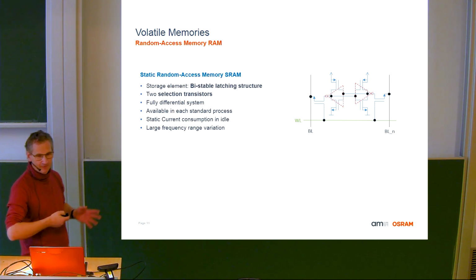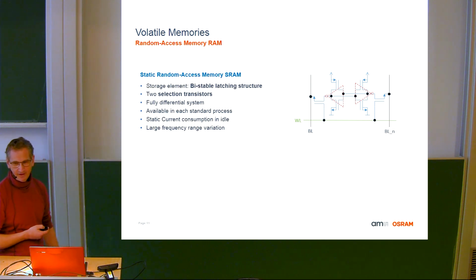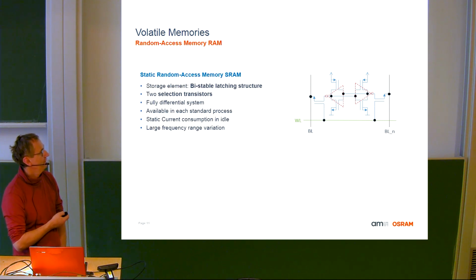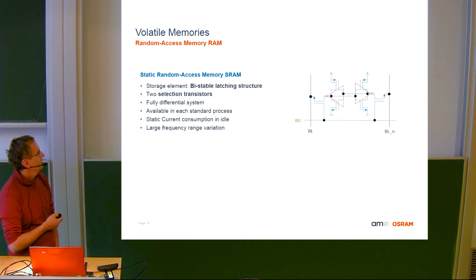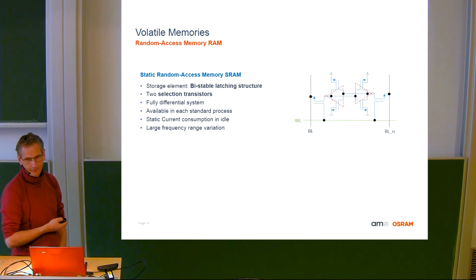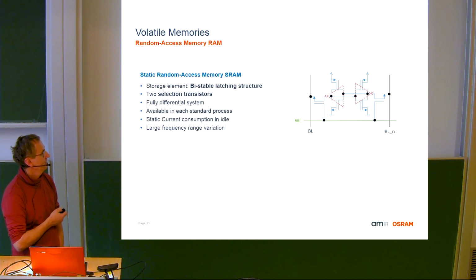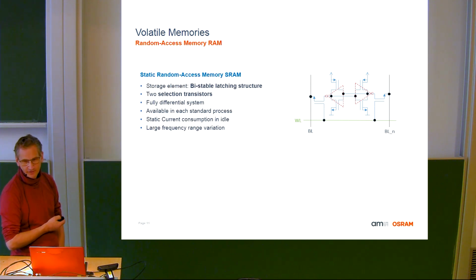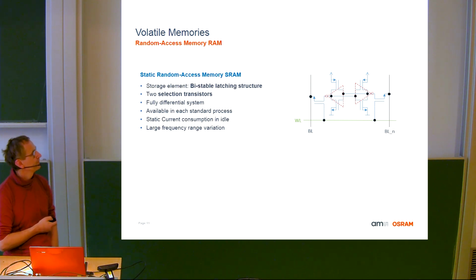So more or less, once you store it, you have to spend some energy to change the content, to overcome a certain threshold so that it switches. Therefore, you need some switches and some lines. These are the word line and bit line. So you then create a memory matrix, and then you can define in which word and which bit line you want to change the content. So you have direct access with these 2 lines to any individual bit.